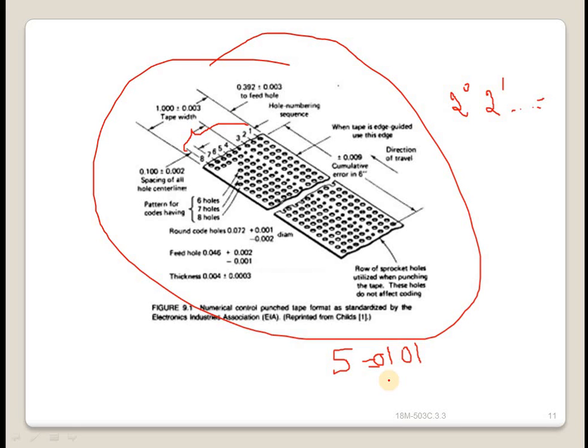Fixed block format. This is the least flexible and probably the least desirable of the three formats. Not only must the words in each block be in identical sequence, but the characters within each word must be the same length and format. If a word remains the same from block to block, it must nevertheless be represented in each block. So this is about the tape preparation.